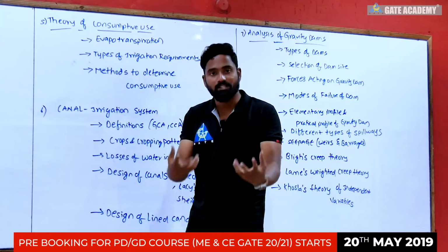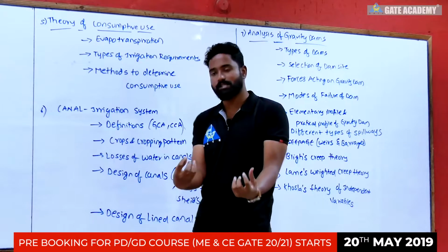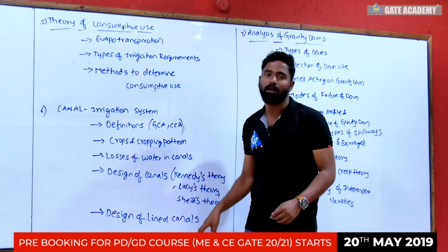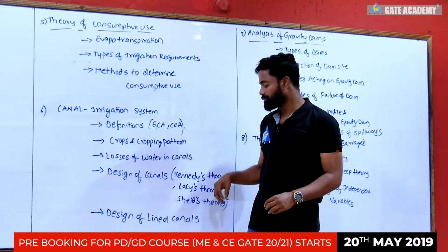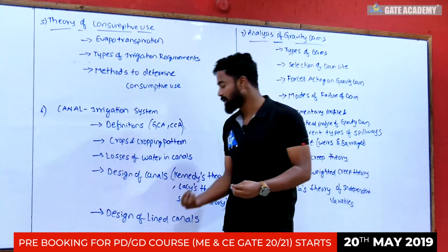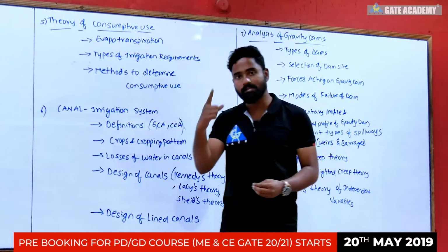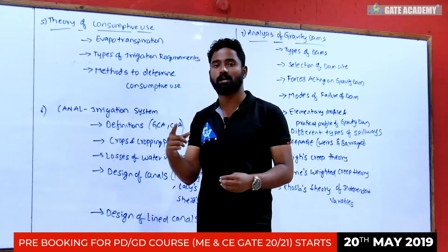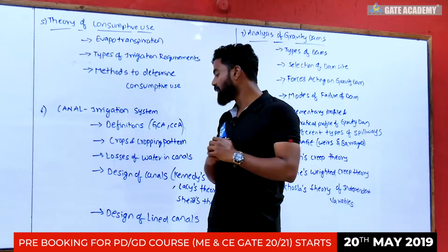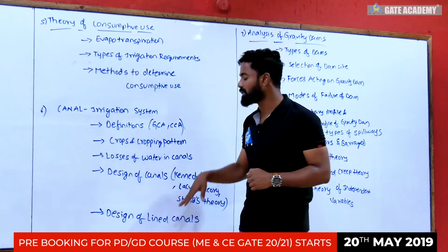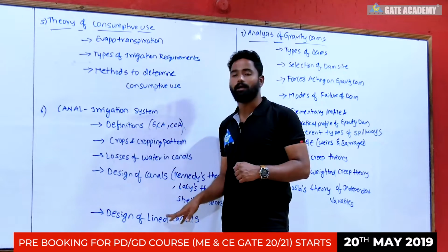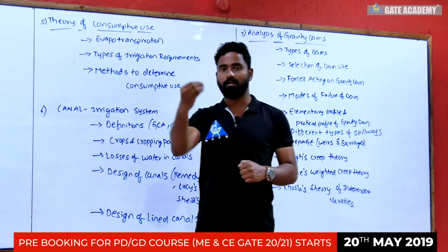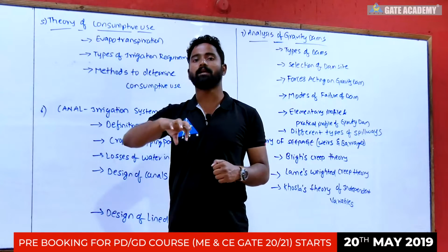The most efficient section or most economical section, you will get from the lined canals. So we will discuss each and every concept in lined canals, like for triangular section, for trapezoidal section, how the lined section will be, and then the economics of the lined section will also be discussed. Economics means if the seepage is less, maintenance will be more.